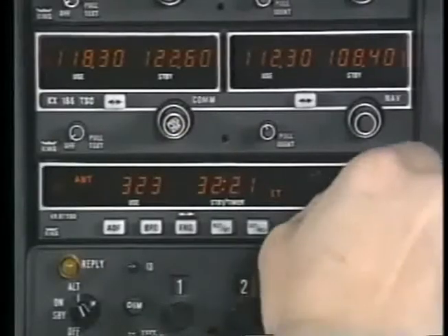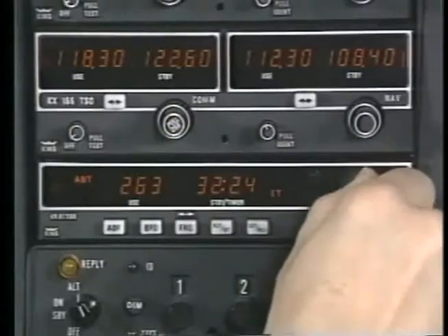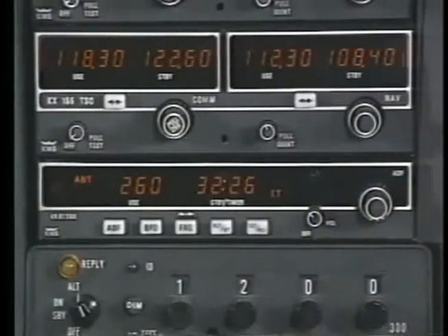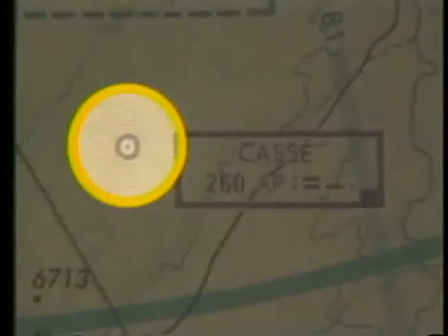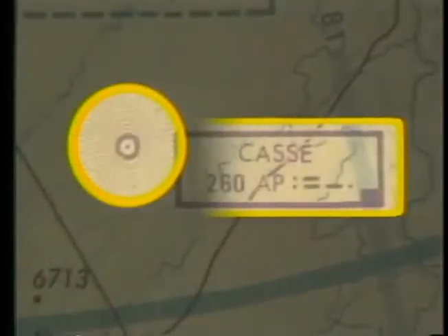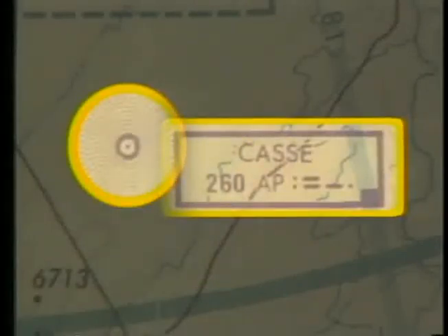With the selector in this mode, enter the NDB frequency in the receiver. You can find station information next to the NDB symbol on an aeronautical chart. The station name, frequency, and Morse code identifier are provided in a magenta-colored box similar to a VOR information box.